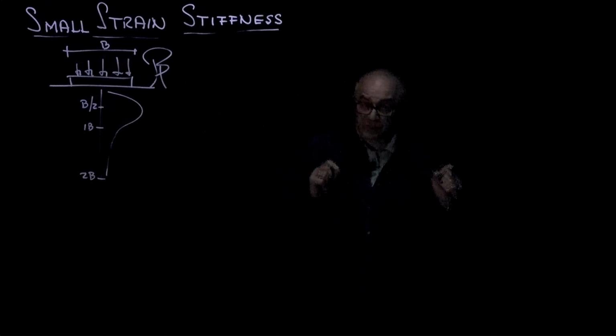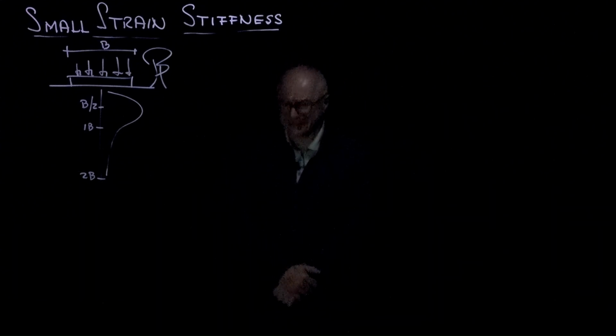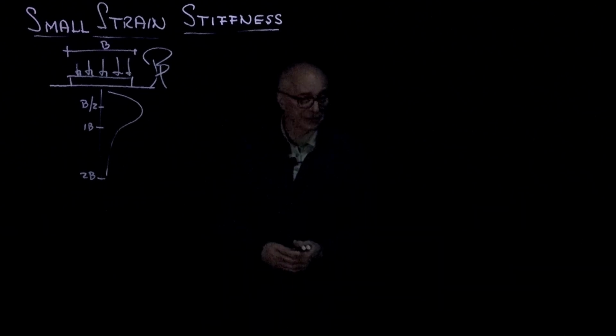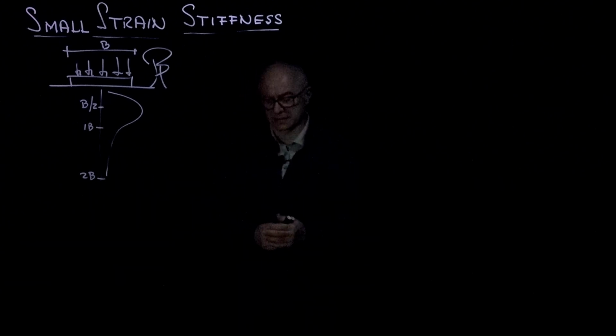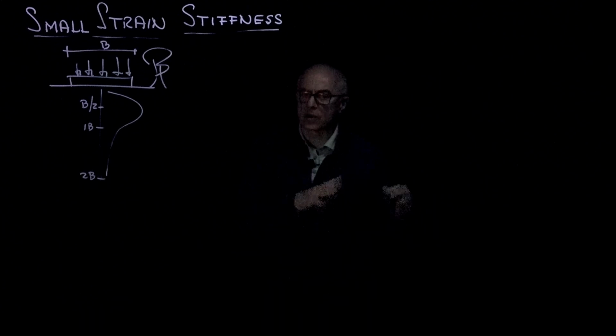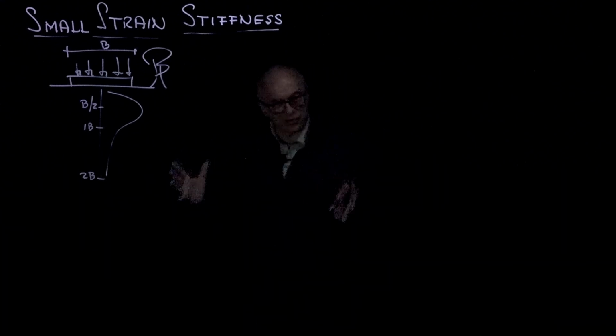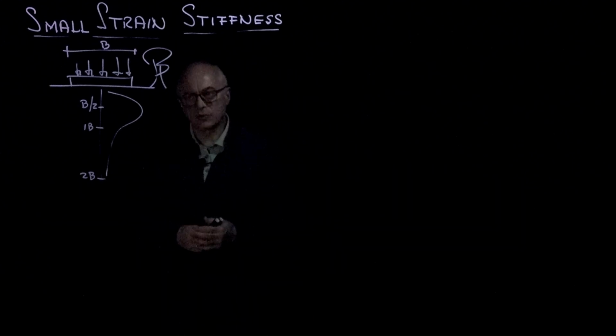Therefore, the small strain stiffness plays a critical role in properly predicting the settlement of footings in general and all our geotechnical systems. Because we design them away from failure, away from yielding, so most of the material around will be in the small strain regime.